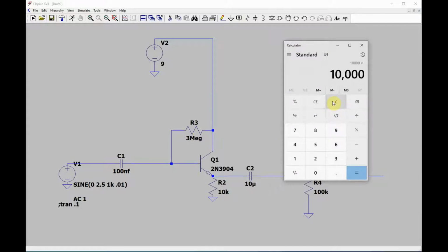If the HFE was like 300, that's 3 megs, and that should put this exactly in the middle. The fact that it's above 4.5 just a little bit suggests that the HFE in this simulated transistor is probably around 330 or something like that.